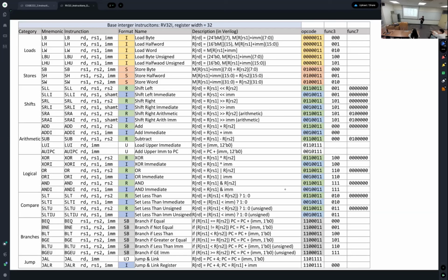Which means exclusive OR reads two operands from the register file indexed by RS1 and RS2 like here. It's the same format, right? But the operation is different. Exclusive OR performs a bitwise exclusive OR operation. Add instruction performs just the add operation, right? It's very simple, right? So only this part is different here, and then the result of the bitwise exclusive OR operation is stored to the destination register, right?